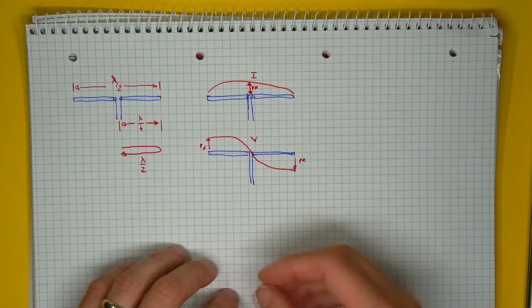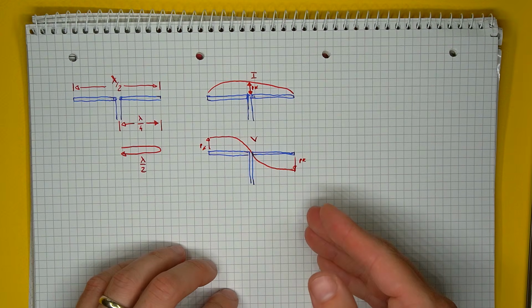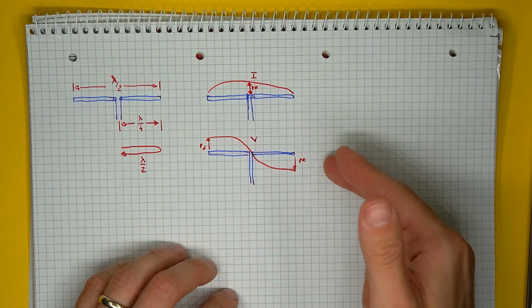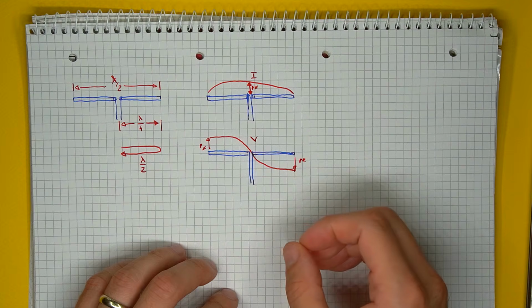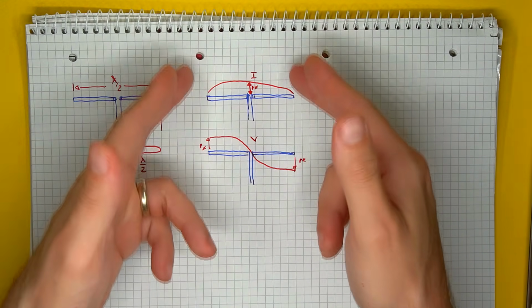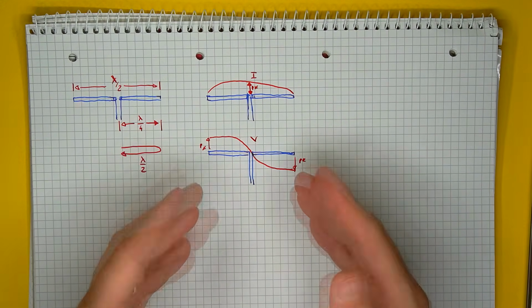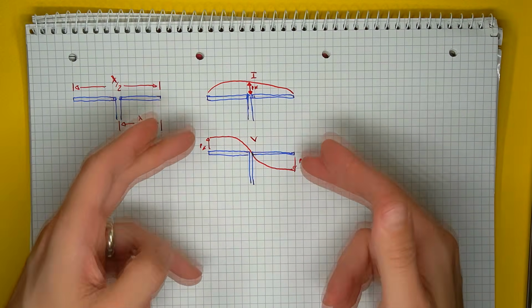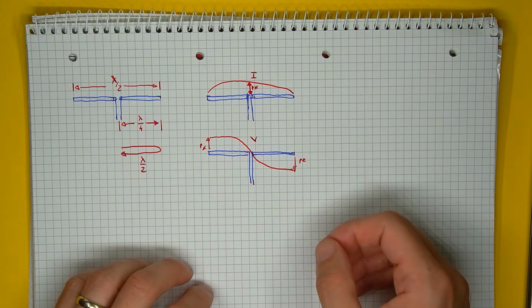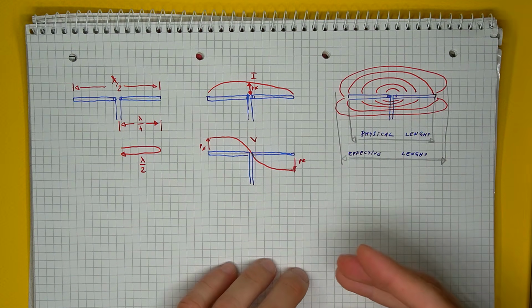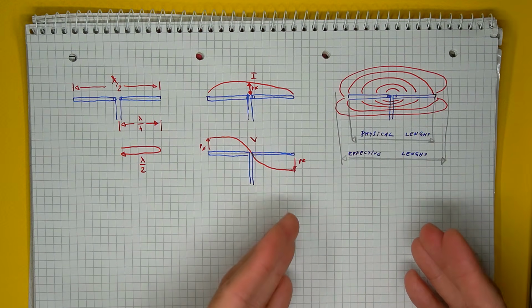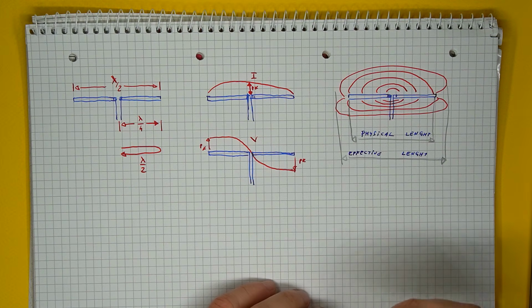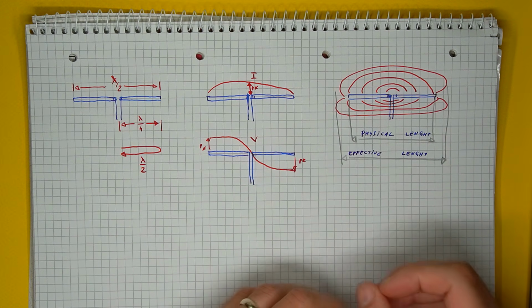In typical explanations about dipoles, especially when highlighting the current and voltage distribution along the antenna, you will see that this current and voltage abruptly stops at the edges of the antenna. So there's a peak current in the middle of the antenna and a peak voltage at the edges. The explanation I found regarding why the half wavelength antenna isn't exactly half wavelength long has to do with the fringing fields around the edges of the antenna.